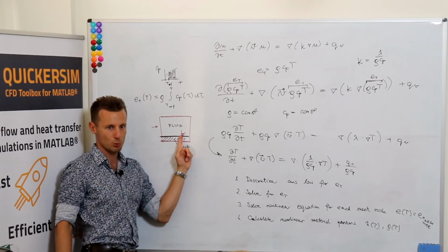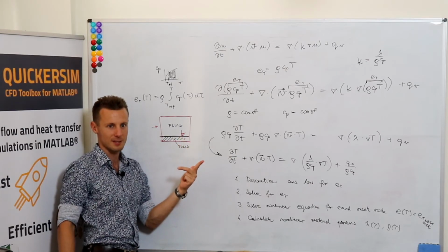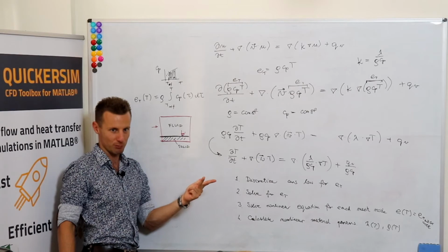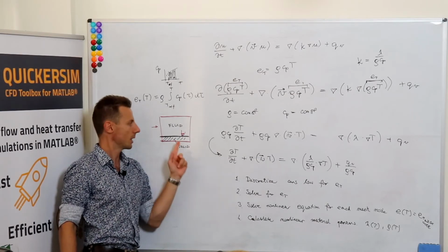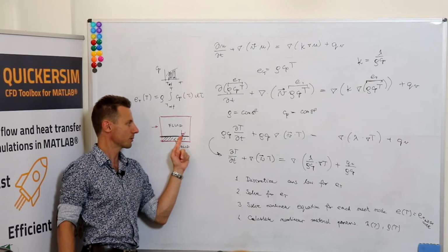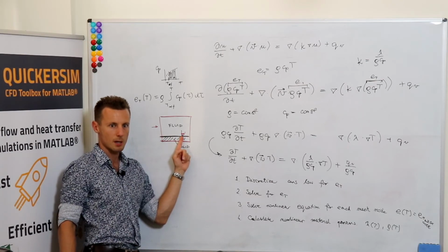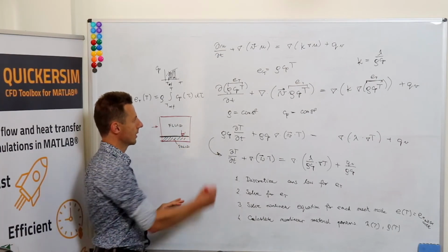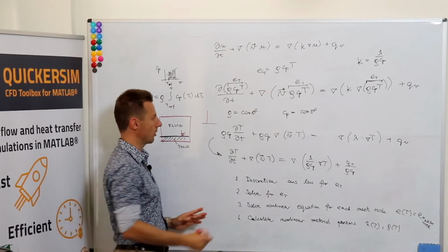And it's up to you and your mesh and representation of gradients, proper turbulence model if you've got turbulence in the system, to discretize the space, generate such a mesh to resolve the boundary layer profile properly. Because what happens with the convective heat transfer is that, let's assume that the fluid is not moving at all.